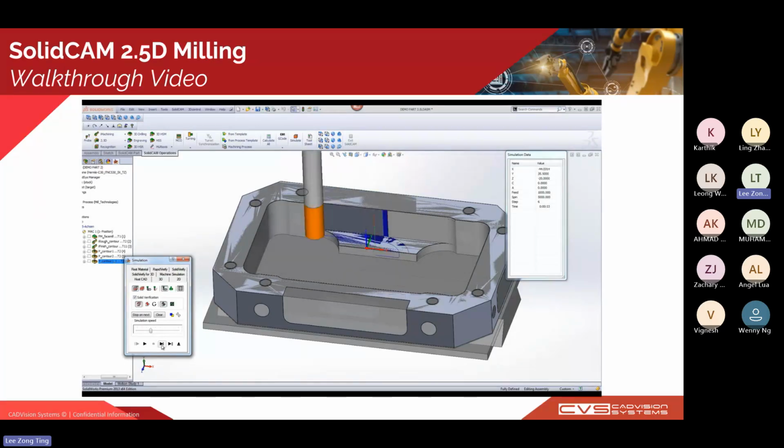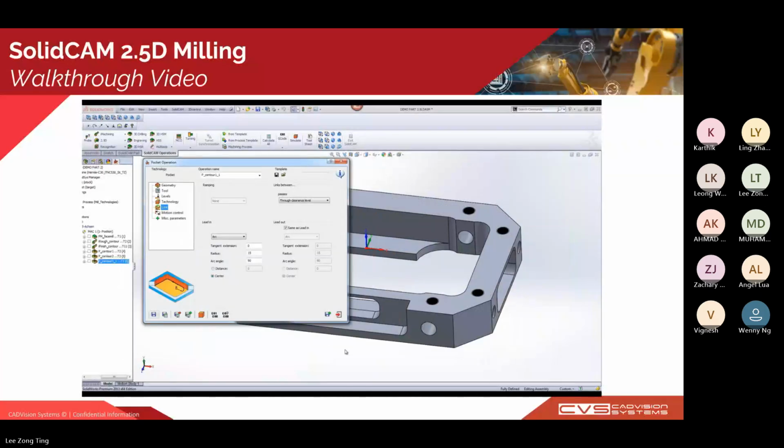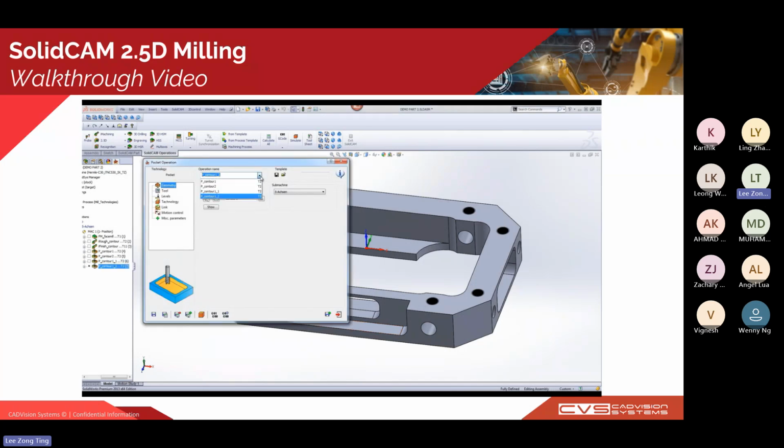So you can see that the tool only machines the rest material left by the first operation. So we are satisfied with this. We go ahead and save and copy and finish pocket number 2. I just change the operation that it is referenced to, so that is pocket number 2.